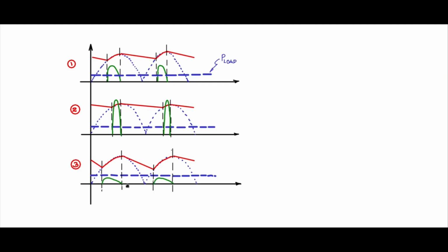We will be trying to increase the current conduction time at the expense of more ripple, and thereby reduce the current peaks and improve the power factor, making it closer and closer to the full conduction as in the case of a pure resistive load. So that's what we would be doing.